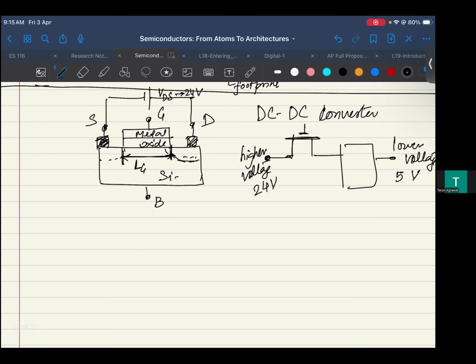That is where people said, okay, I would need in this transistor a region specifically for dropping these voltages. One way you could think of this is, let's say this is your metal oxide, which still remains, this is the semiconductor, this is your source contact, and there's a pocket here.